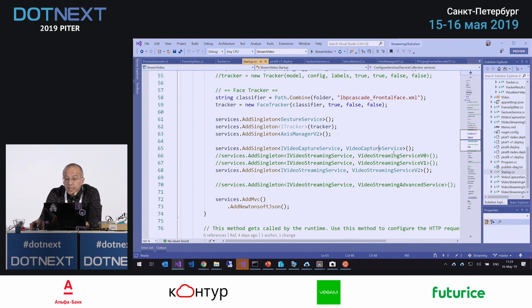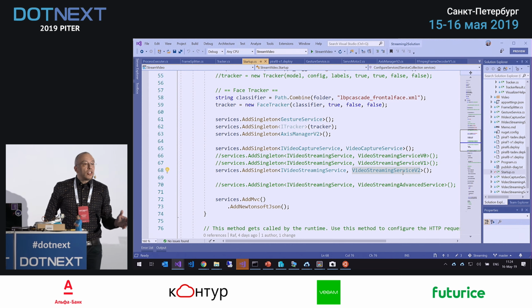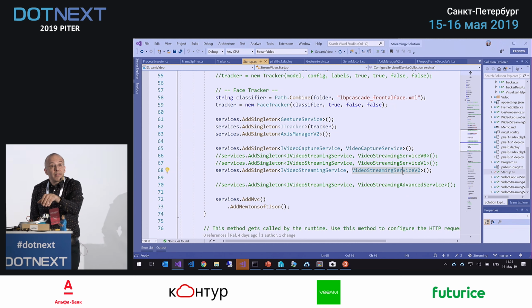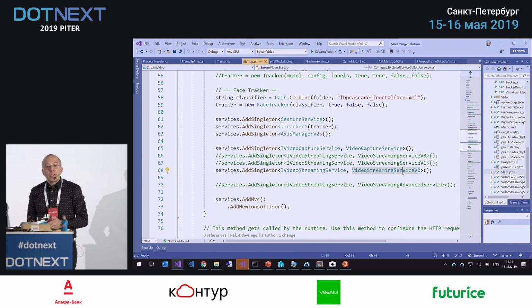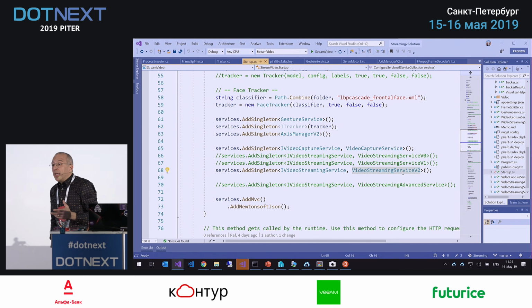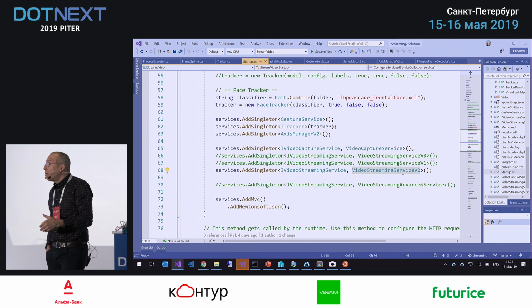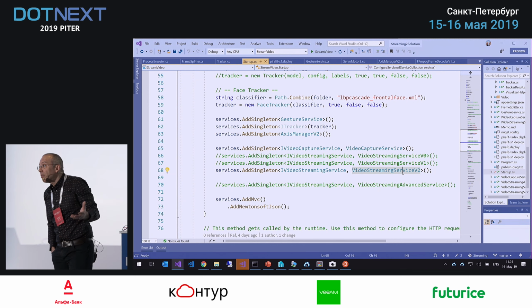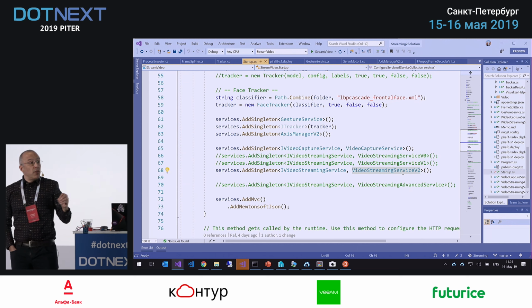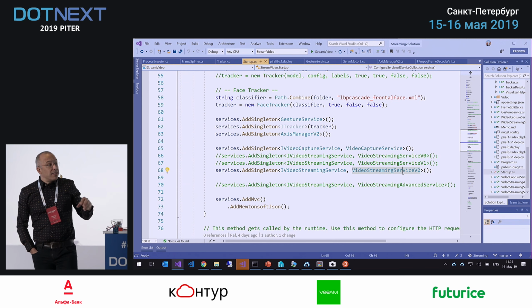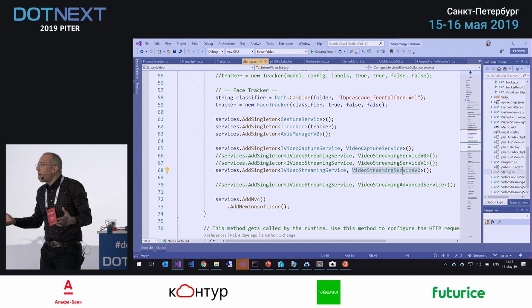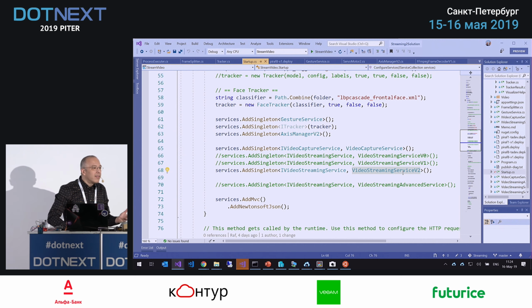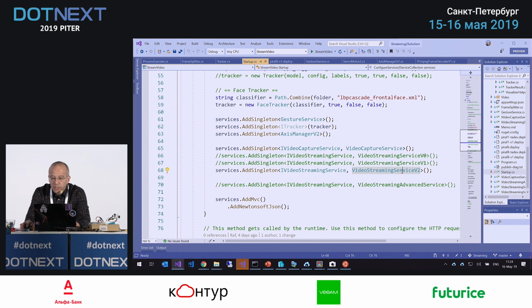And then I have different capturing services. I also tried, you may know that OpenCV also manages the camera by itself. It can drive the driver of the Raspberry Pi directly. Unfortunately, and it is well documented on GitHub, they have a leak. It rapidly goes out of memory because OpenCV has an open bug that has not been fixed yet. So the trick of using standard output from a separate process was absolutely the best choice. It minimizes the amount of code that you have to write, and it doesn't have leaks, which is pretty good.